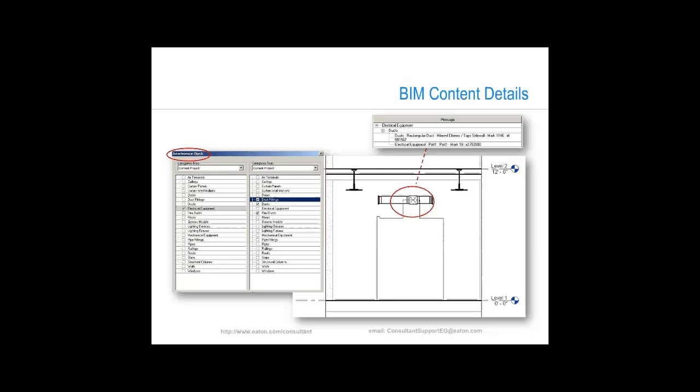While the use of these CAD images, and I'm talking about 3D CAD images, does allow visual design, in other words, it allows the user to visualize these 3D objects within the building, these CAD images are considered merely graphical objects. In other words, they lack any data. Using these non-intelligent CAD formats may also hinder other very powerful features in the BIM software packages, such as collision detection.